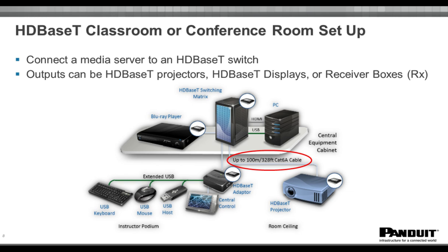One thing when you're using the HDBaseT functionality in a projector that you need to remember is that you're going to need to apply power to your transmitter side of your HDBaseT system. The projector will not be able to supply power to your transmitter, or you're not going to want it to because it can actually burn out that transmitter.